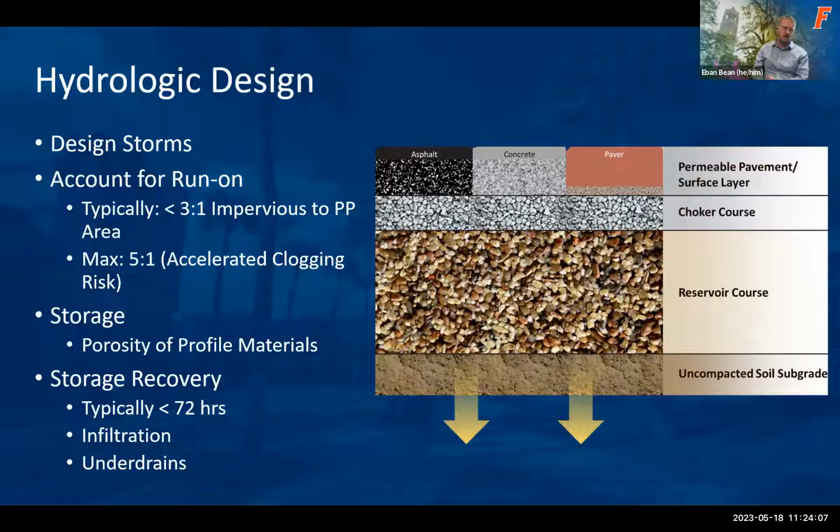With storage recovery, this is where the subsoils come into play if that's how we're draining the system or recovering it. We can have it as an underdrain, and I'm not addressing that here, but that's essentially hydraulics limited by the grade, slope, and diameter of the pipe. With storage recovery, we typically are looking at somewhere between 24 and 72 hours with these systems.